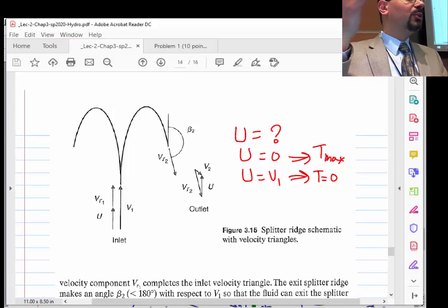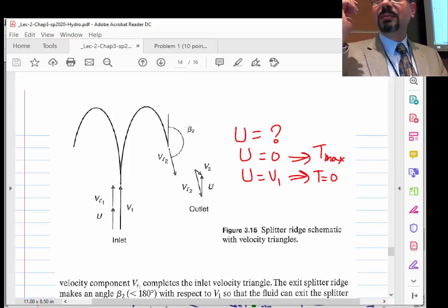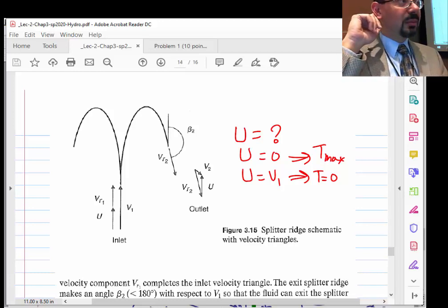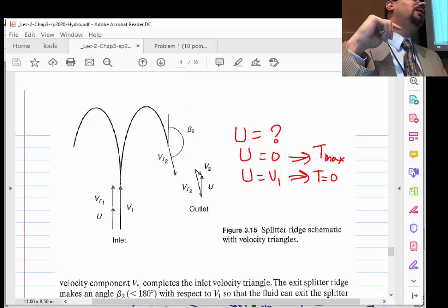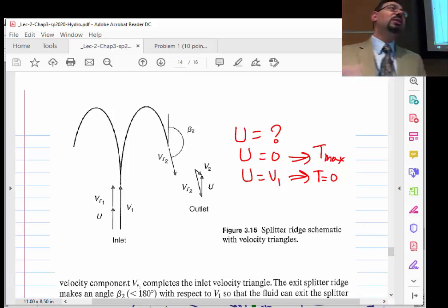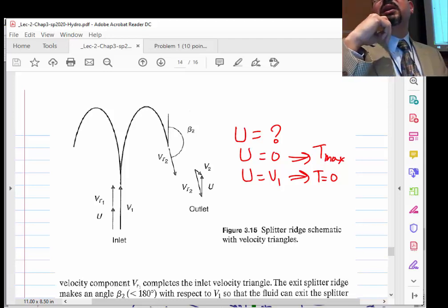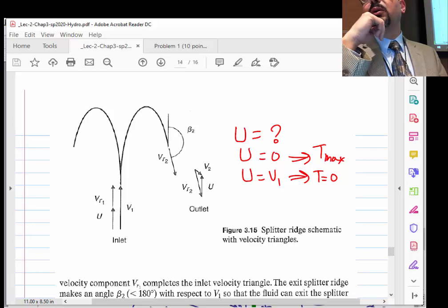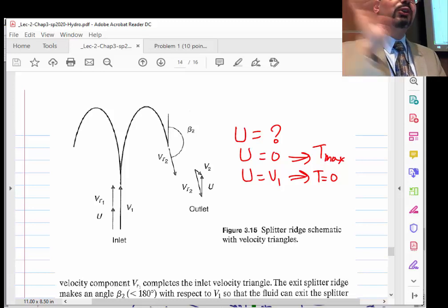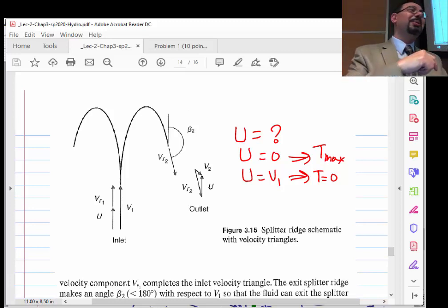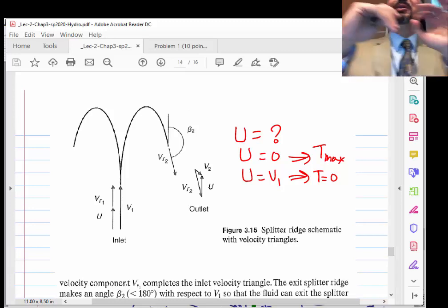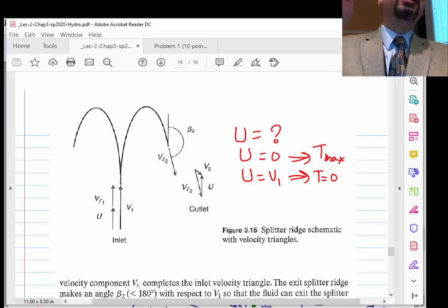So what happened to the pump if you turn it without water in it? What do you think happened? It spun too fast for the bearing. The bearing is not designed for that RPM. So the bearing ended up getting damaged. Rumor has it that the boss actually knew this would happen and set him up because he hated him, so he just waited for the right moment. That is a rumor. But anyway, what do we learn from that story?